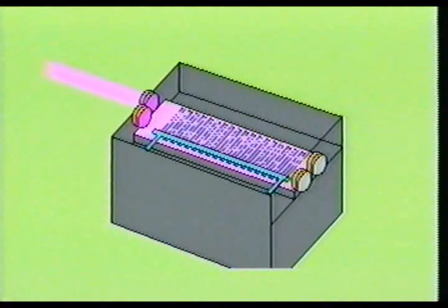When the CO2 gas laser system is energized, the electrical discharge between the cathode to the anodes will cause the nitrogen molecules to become excited. This upper vibration energy from the nitrogen is then transferred to the carbon dioxide molecules through the means of collisions from the photons being emitted from the nitrogen atoms. As the energy is transferred to the carbon dioxide atoms, they become excited as well. When the energy from the CO2 atoms falls to 2 lower levels, they emit photons at wavelengths of 9.6 microns and 10.6 microns in the process. Once the electrons have fallen to their ground state, they become excited again, and the process starts all over.